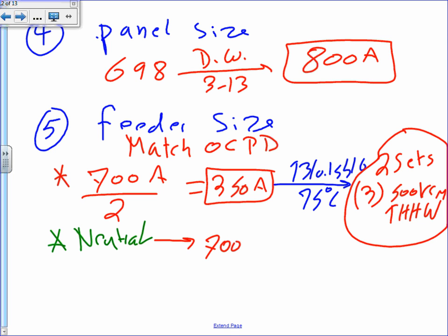Unless, for this one, guys, here's what I tell you, you want to go and eliminate like we did it in the proper way. Let me tell you the proper way. The proper way is to go and eliminate all the neutrals that we did, and all the loads, the three-phase neutral. In this case, it probably would make a lot of sense to do it this way because we have full control over the load. But if you don't know what your load is, if all you have is just a lump sum panel and you want to size a neutral for it, you just take the 200 plus 70% of everything higher than that. But since I already know my neutral load, let's go at it.